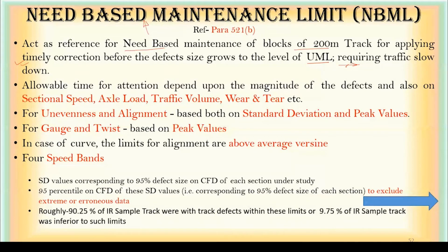What is the general track deteriorating rate in those areas? What is the condition of track fittings, track structure? Everything will affect the time required to attend to that localized defect. So that has to be decided section wise, but normally it should be done within 15-20 days. Because if you don't do it and something happens, a caution order applies, then you have to reply also.